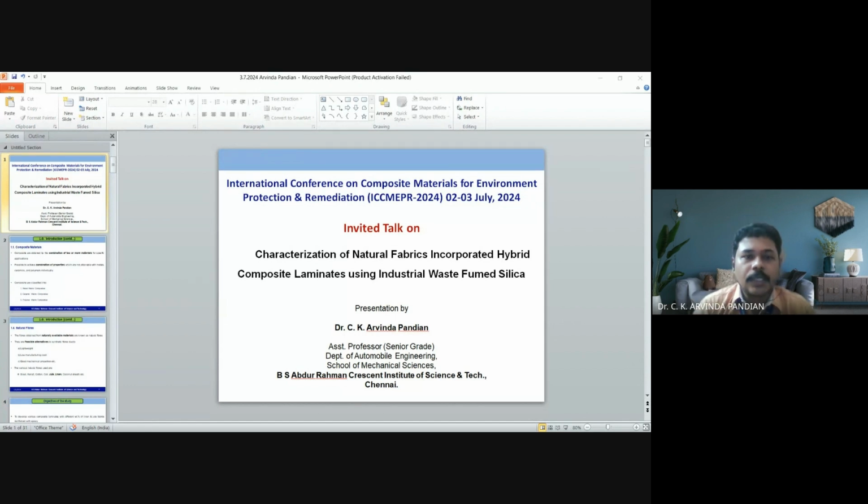So, composites are materials formed by two or more materials in order to target specific applications, which is not possible by a single metal, ceramic, or polymer. Natural fibers are the reinforcement I have used here. They are feasible alternatives to synthetic fibers due to their lightweight, low manufacturing cost, and properties. There are many natural fibers available, starting from sisal, kenaf, cotton, coir, jute, and linen. In this study, jute and linen have been used as reinforcement.